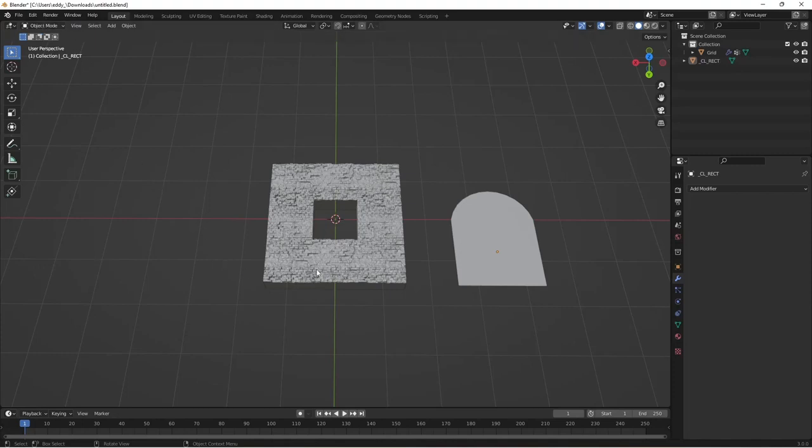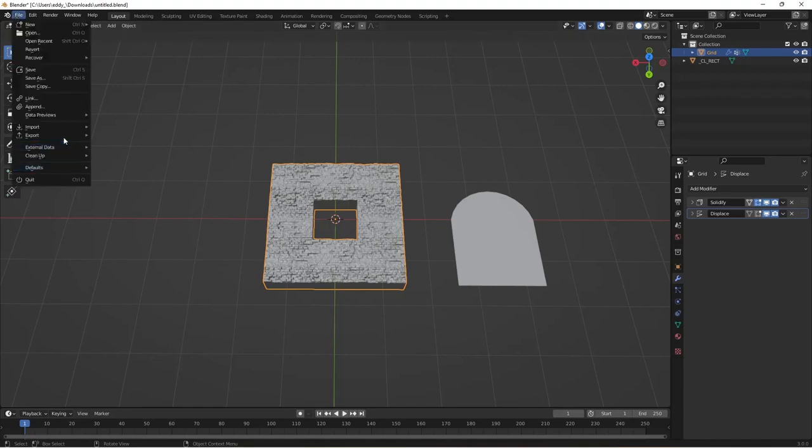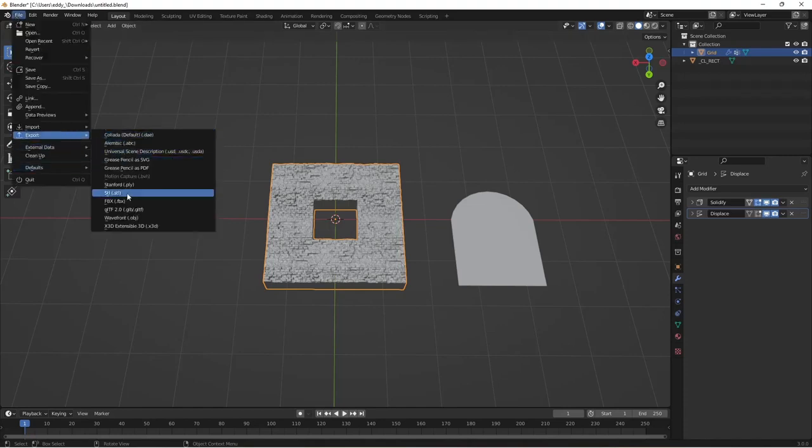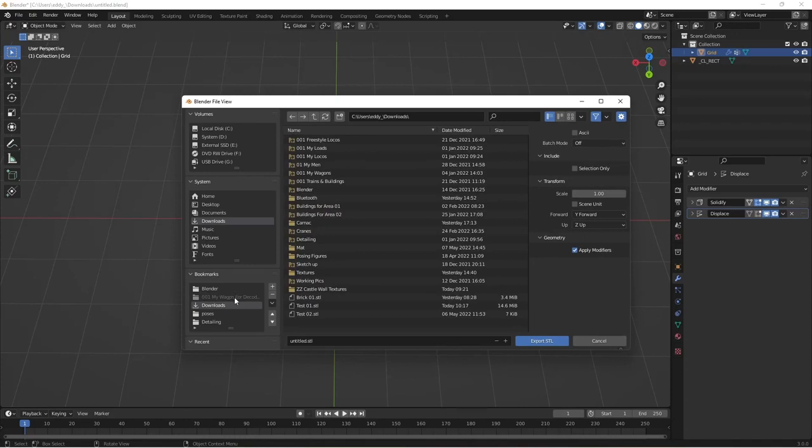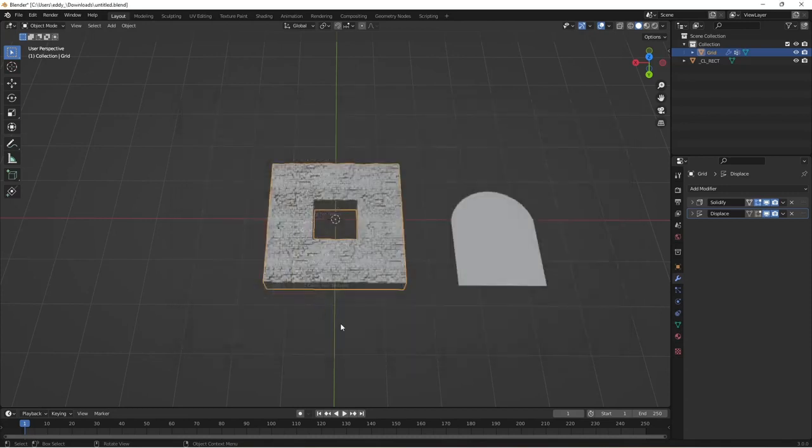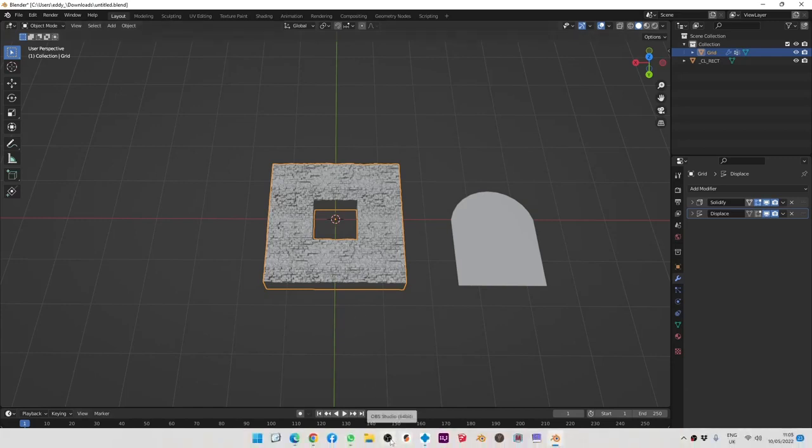Right. Now we want to save this object for printing or an STL now. So if we click on it, File, Export, come down, STL. Now important thing is, on the right hand side, click on Selection Only, because otherwise it selects everything in the scene and you don't get your result you wanted. I'll just double click on test and it's saved it as a test.